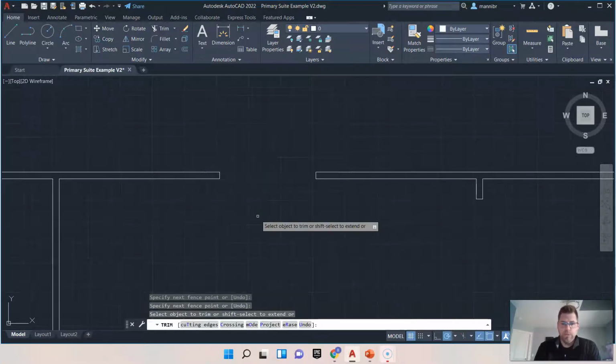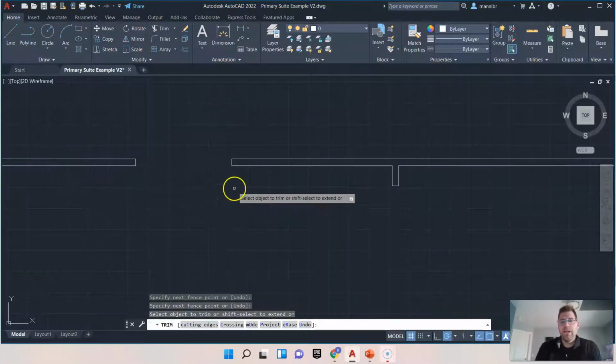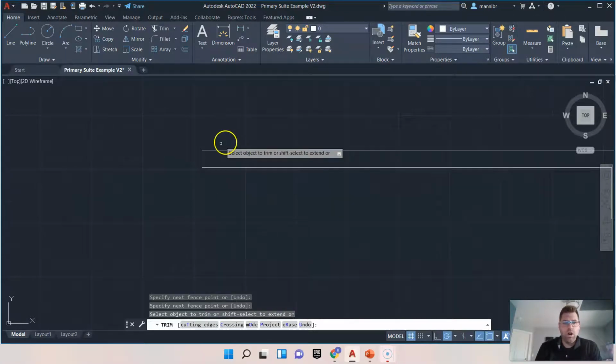So there's my window opening. And then I'm going to add a 3-footer over here and a 3-footer over here. Now I need some wall left in the middle. I'm usually going to need a trimmer and a king, and probably a trimmer and a king. So that's going to be 6 inches minimum.